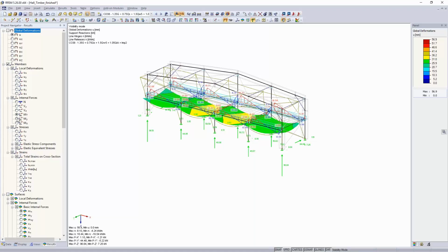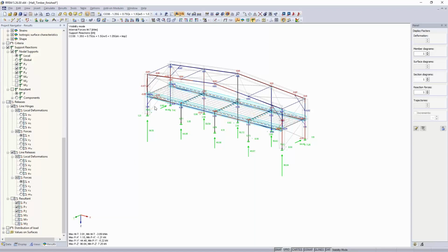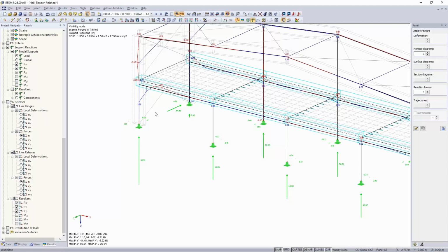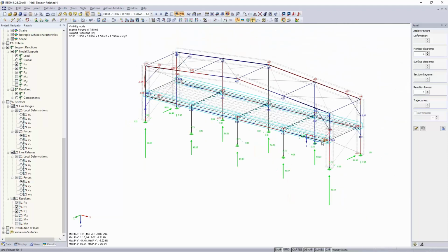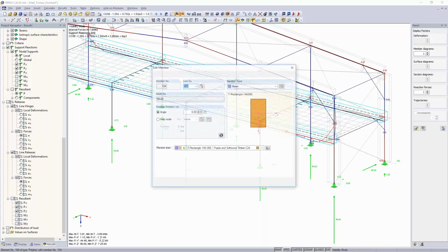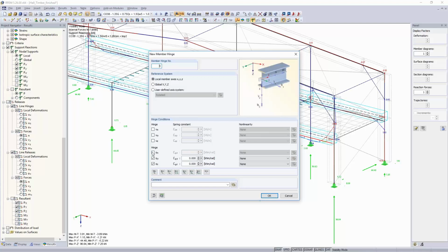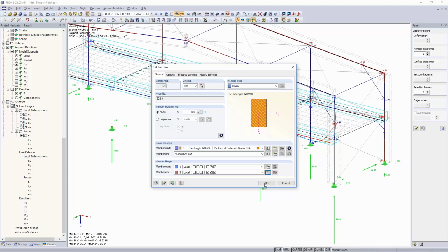In members, torsional moment, and maybe we switch off the releases. You see that we have a torsional moment of nearly 4 kilonewton meter on the edges. And it's clear we forgot to put the degree of freedom here. It's only the degree of freedom for the moment in Y and Z direction, but not for torsion. So the phi x on these edges also needs to be given the degree of freedom of 0, which is always the case in timber design. Yes, that requires that I delete the results.